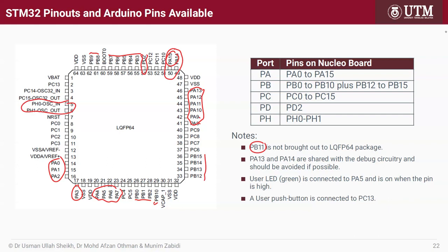The user LED just now is connected to PA5, and that is the pin here. The LED is connected here. And the push button is connected to PC13. So the switch is here on the Nucleo board. We have already used these two pins commonly.